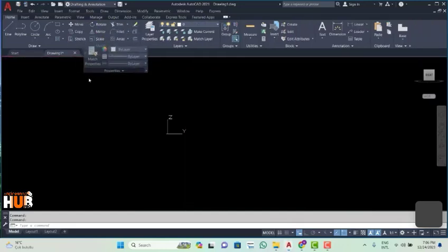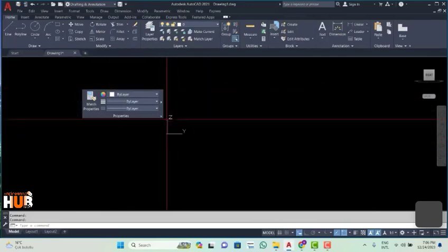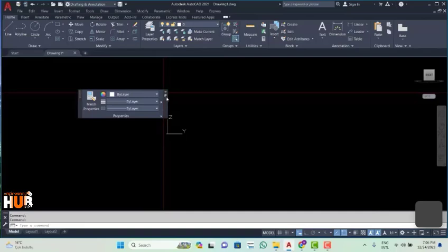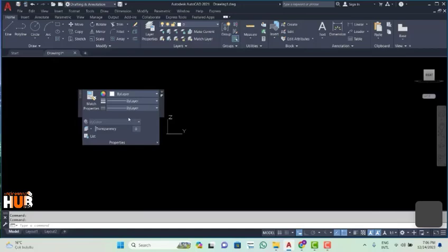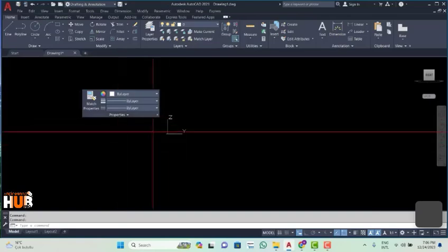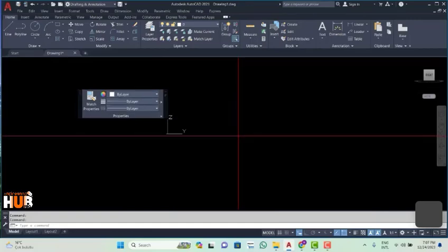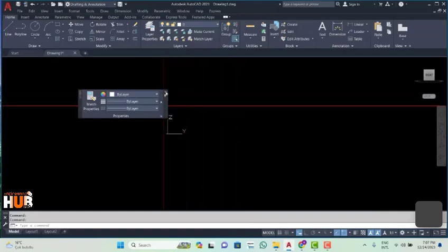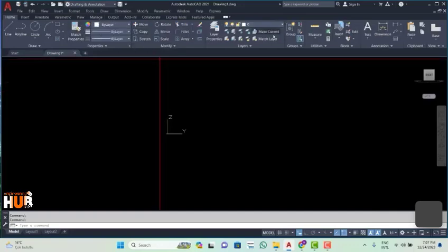Also, you can drag the title of the panel to make it a floating panel in the drawing area. Also, you can adjust the toggle orientation of the panel by pressing this one. So you have this down arrow to show all the commands included in this panel. By clicking the down arrow, it displays to the bottom. If you click the toggle orientation again, it will display to the right. You can also return this panel to its location by clicking this up arrow here, so it comes back to its location in the ribbon.